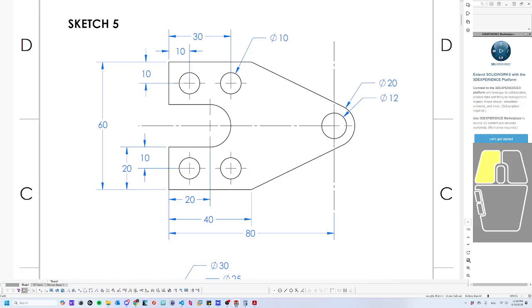If I move, this point here can move all the way like that, but I want it to be a smooth transition between this line and this arc. Anytime you want a smooth transition, if you pick the 2 things you want to smooth out, if one is an arc and one is a line, the relation that smooths them is the tangent relation.